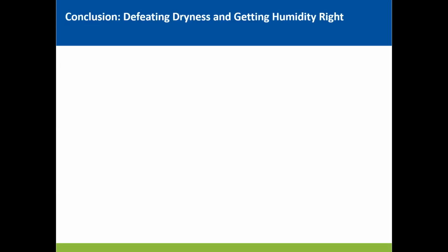So to wrap everything up and summarize, we covered really 5 main topics to know here today. First and foremost, building dryness occurs when the outside is drier than our target levels indoors. So whenever the absolute humidity outside is low, we'll have a drying effect. When we're bringing in lots of outside dry air, that'll have a drying effect. But typically we're going to see that in the winter seasons when the air becomes very cold.